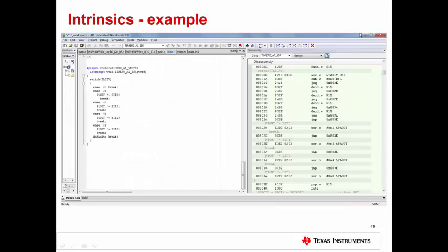This example shows the code generated by a switch statement checking for different values. As can be observed, the assembly takes 4 instructions to do the first comparison, but the time taken for the different cases varies. With a value of 8, it takes 21 cycles to execute the corresponding instruction.